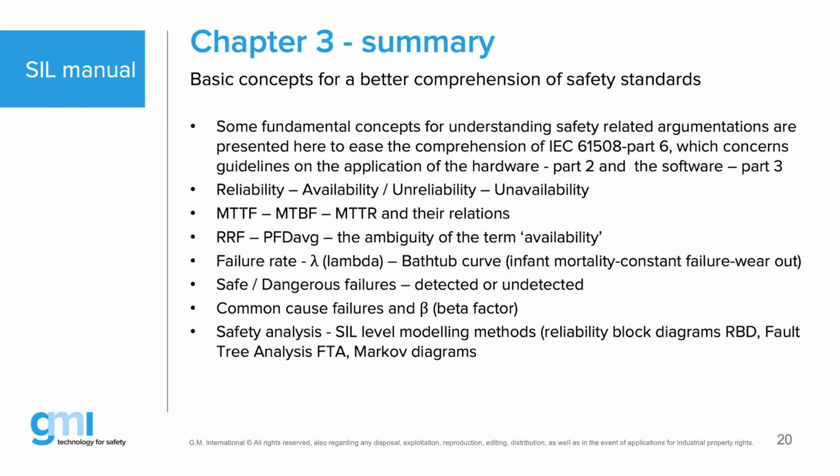In chapter 3, that is more for people who are a little bit more advanced, in the sense that you will try to understand, you may get some documentation from your vendor, you may get a functional safety data sheet, or some reports, some numbers, and you will see all kinds of abbreviations. Some of them will be clear to people who have heard this before, but here you will see the MTTF, the mean time to fail, the mean time between failures, that's the MTBF, and the mean time to restoration, which used to be called the mean time to repair in the older edition 1, but since 2010 they changed that in the 61508 edition 2.